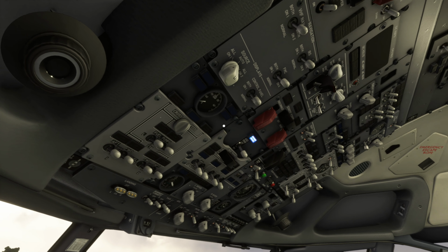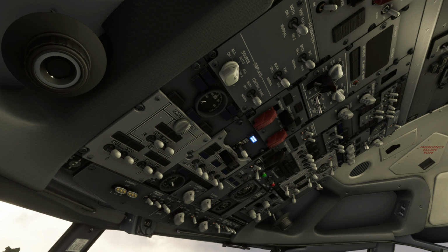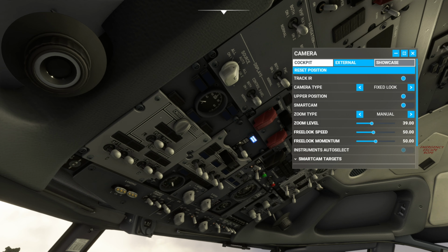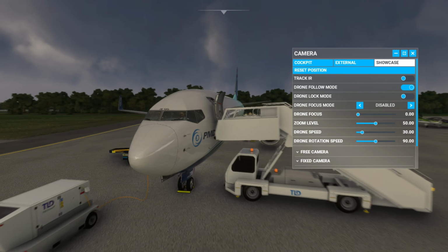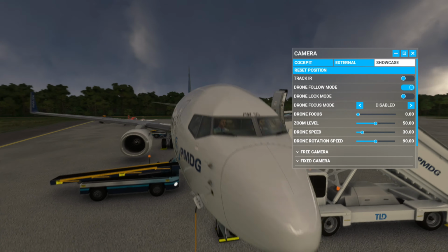We have got 3 primary means of generating electrical power and thereby hydraulic pressure on the airplane. The ancillary control surfaces on the 738 are the flaps, slats, and spoilers. They are actuated by hydraulic pressure. Hydraulic pressure is activated and generated by electrical and engine-driven pumps. Power for those systems is generated by the 2 main engines, the engines that are mounted on the other sides of the wings.